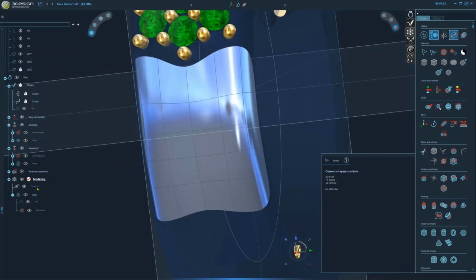Once you've added this new edit surface, like I was saying before, don't go back and change the original. There is no parametric link between those surfaces. It'd be almost impossible to figure out how to connect those things. So don't edit this one anymore. Make sure you're finished with this one. We can always remove an edit if we need to go backwards, but you have to destroy the original or the top one to go back. So it is a linear history. Don't skip around like you do over in 3DESIGN.